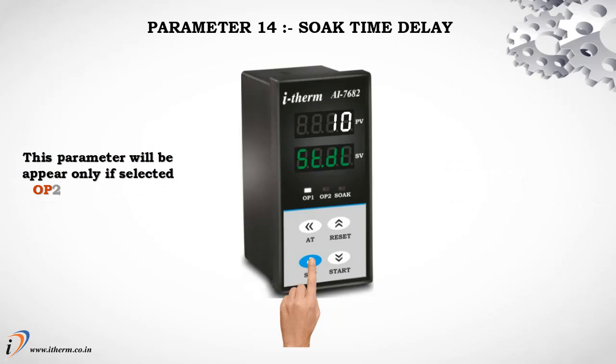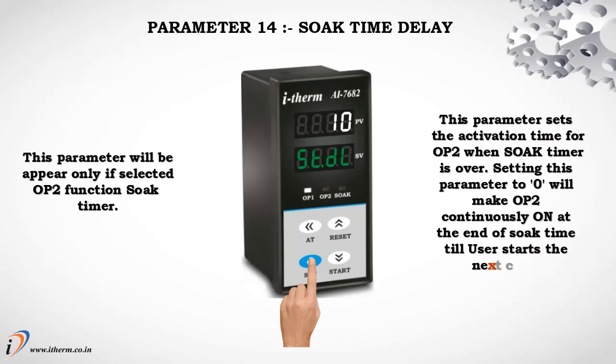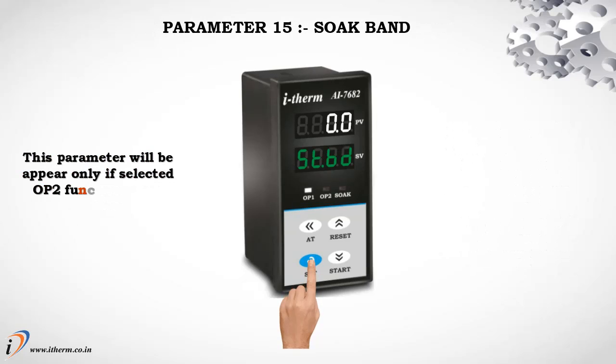Parameter 14, Soak Time Delay. This parameter will appear only if selected output 2 function is soak timer. This parameter sets the activation time for output 2 when soak timer is over. Setting this parameter to 0 will make output 2 continuously on at the end of soak time till user starts the next cycle.